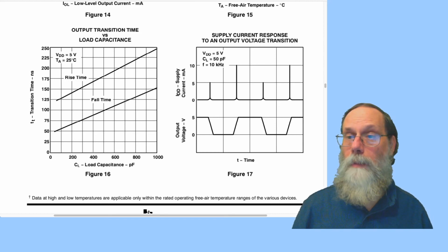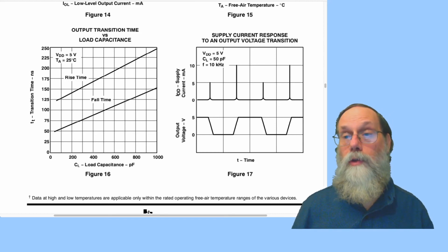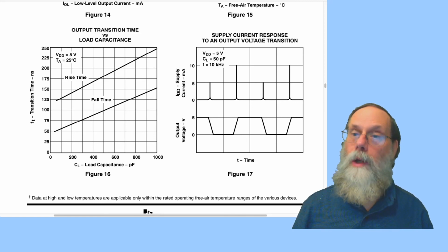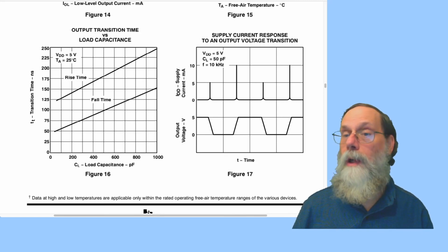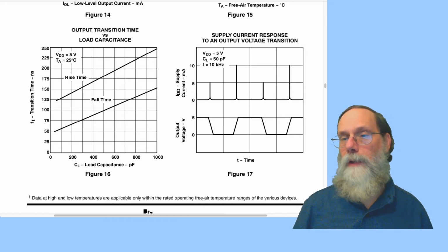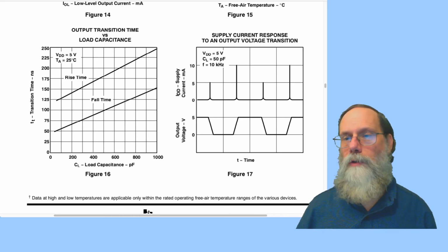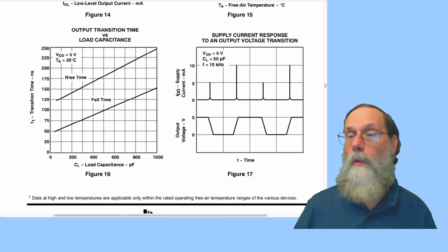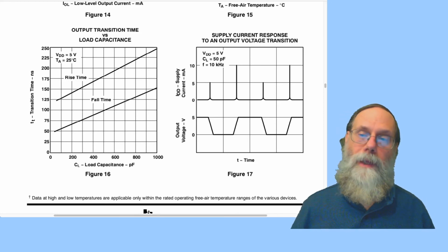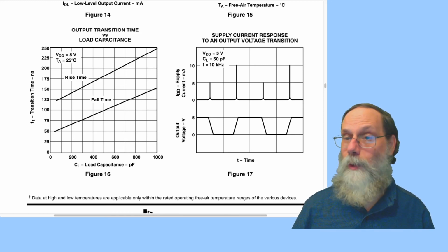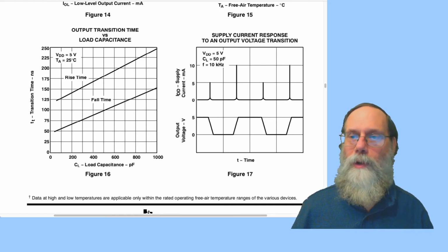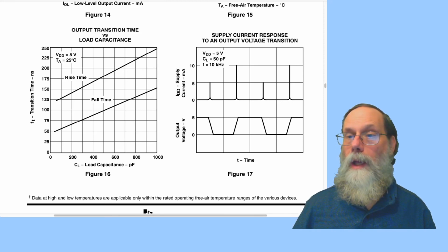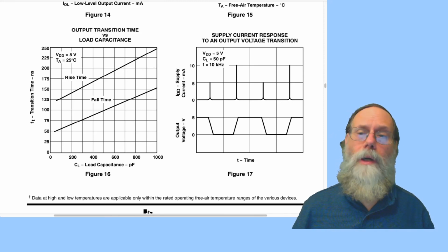For the lab, one of the things you'll be doing is looking at driving the NFET and PFET with a comparator, this comparator, or with a comparator driving an inverter that drives the field effect transistors, and looking at the difference in how fast those transitions go. This will give you a nice way to estimate what you expect to happen, and the measurements should, if things work nicely, confirm your calculations. And I think that's all we really need right now on comparators.